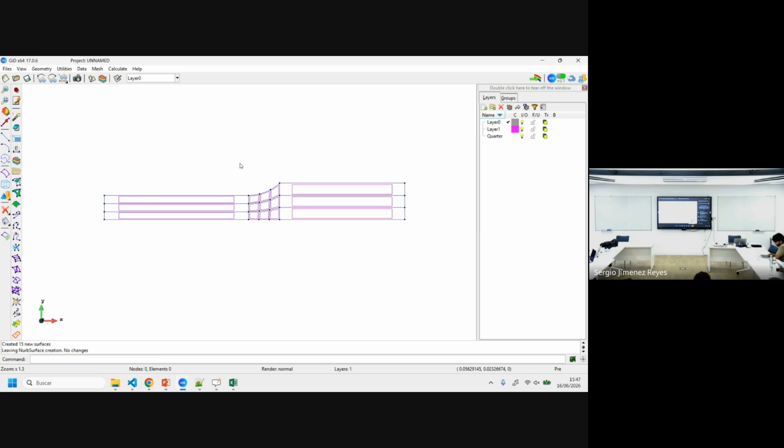So, what you should do is, if you want to calibrate the threshold function, what I would suggest is that you open the CSV file, create a chart, and then propose a list of points that match the behavior in terms of strain and stresses for this nonlinear regime.